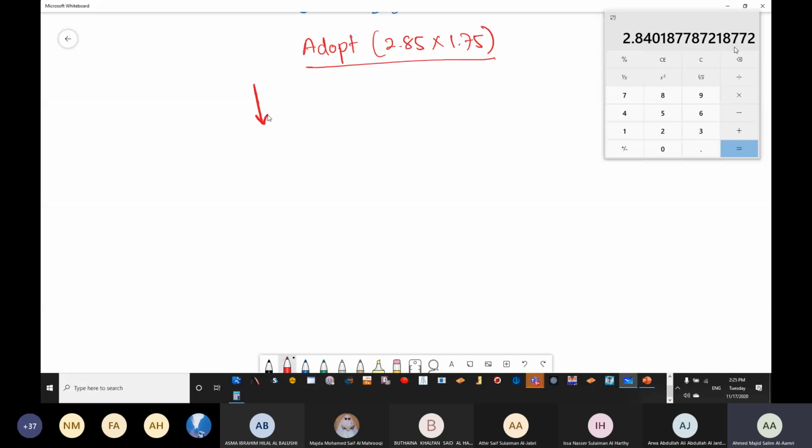We said if the load is coming at the center, it's going to be P over A. And if the column or the element is not at the center, then we have P over A plus or minus M over Z, or P over A minus or plus 6M divided by BD squared. Do you remember that we have talked about these things?